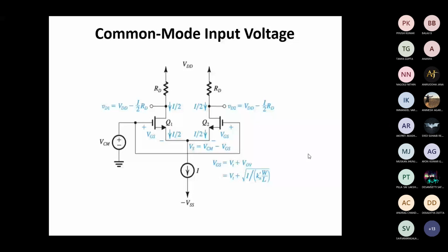Okay. So theoretically, the common mode output voltage will be 0. See, it will not respond. But in the practical scenario, we are getting some output. Did you observe in the simulation? We are getting some signal in the microvolt or nanovolt range, right? So the common mode gives you negative gain. In the ideal case, the output voltage will be 0.